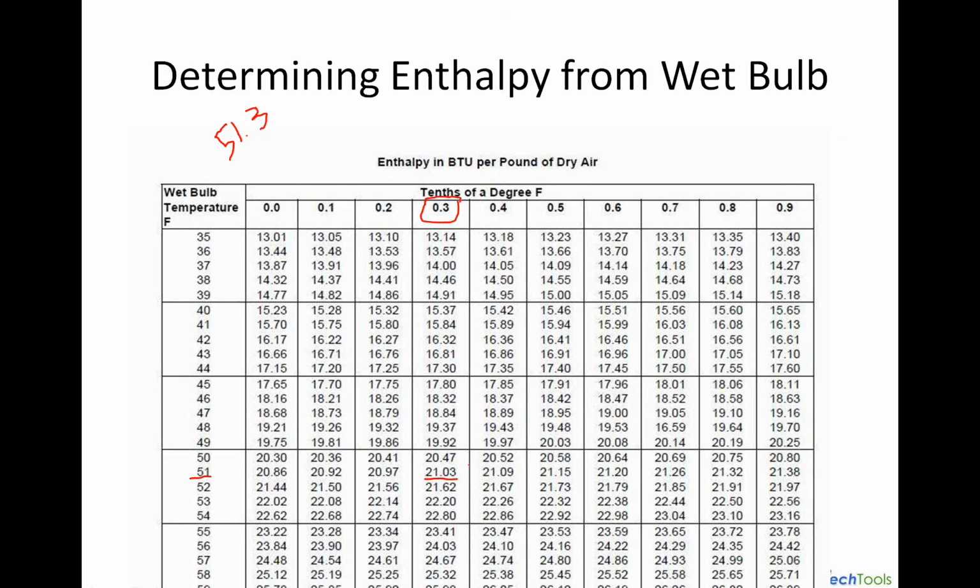The Testo 605H2s, if you set 2 of them side by side, and you really have to put them almost in a plastic bag or a baggie to let them stabilize for a second, you'll see they're usually within 1/10 of a degree of each other.